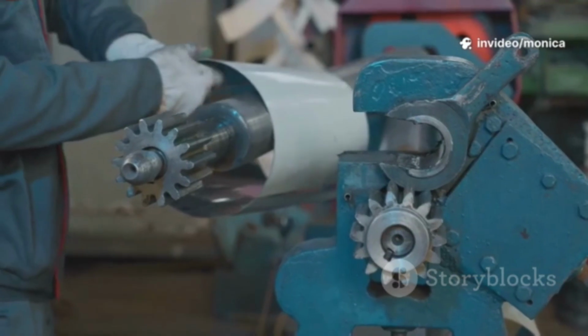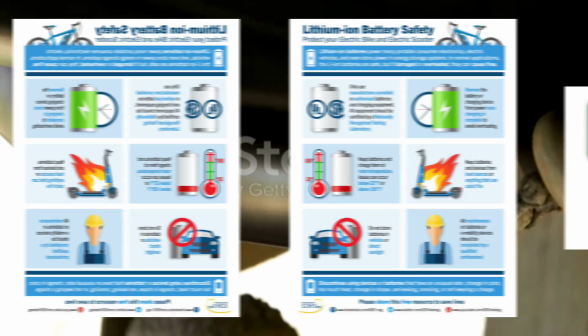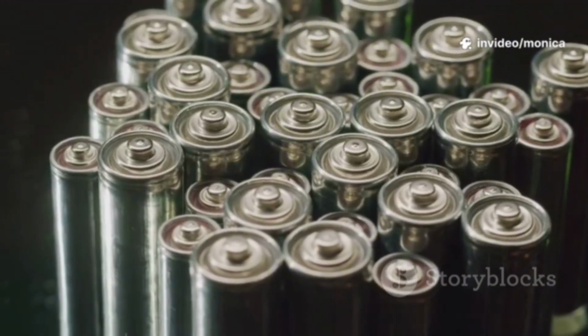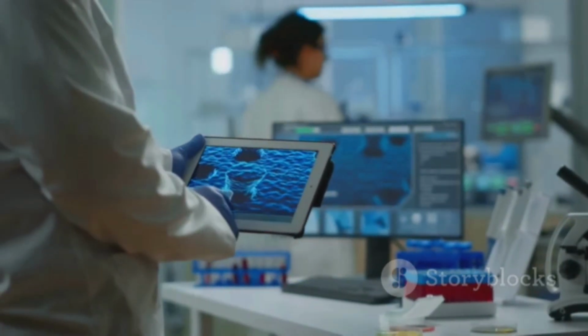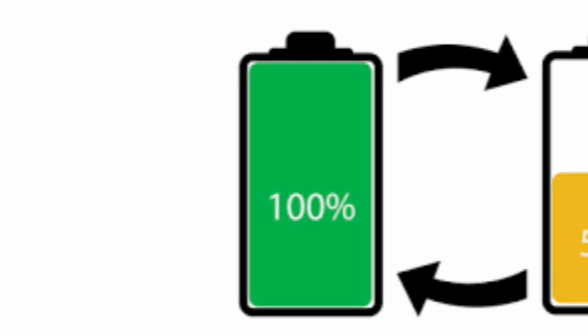For testing procedures, after formation, extensive testing is conducted to verify the performance and safety of the battery cells. These are the common testing types. Capacity testing measures the total energy capacity of the cell, ensuring it meets design specifications. This is typically done through a series of charge and discharge cycles.